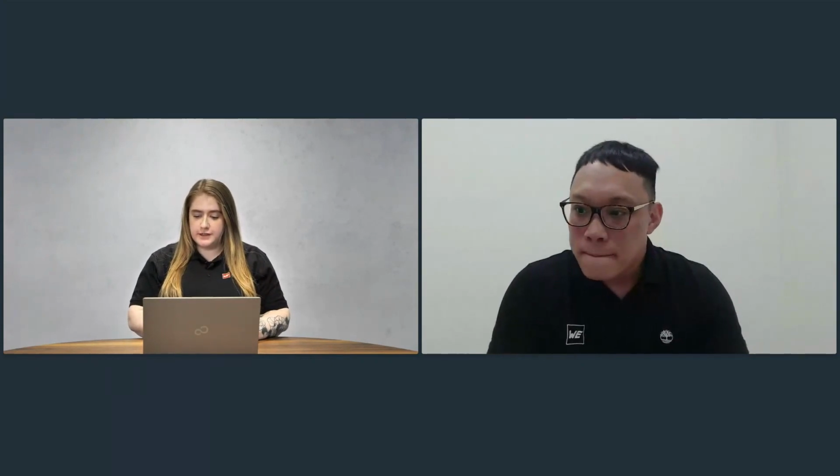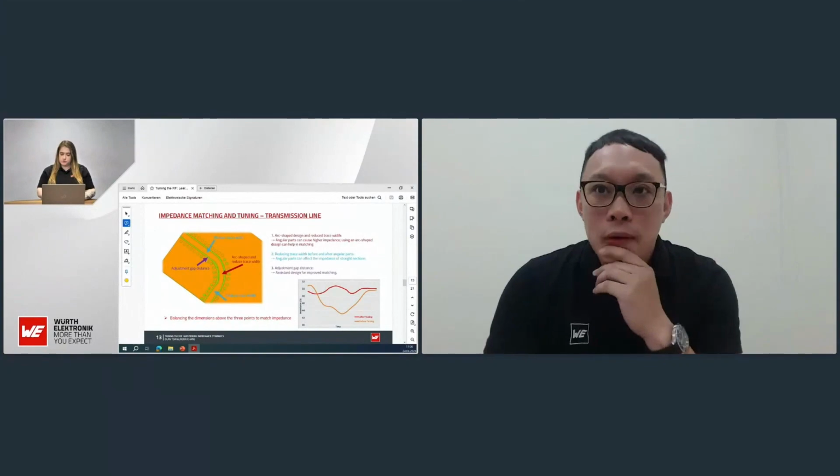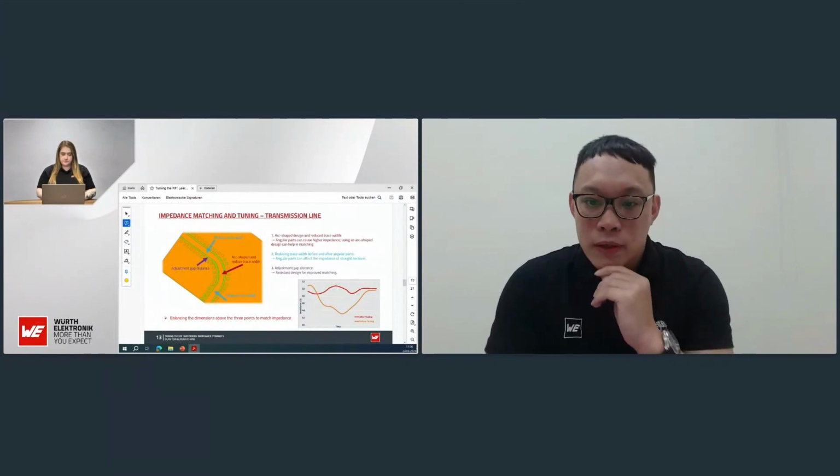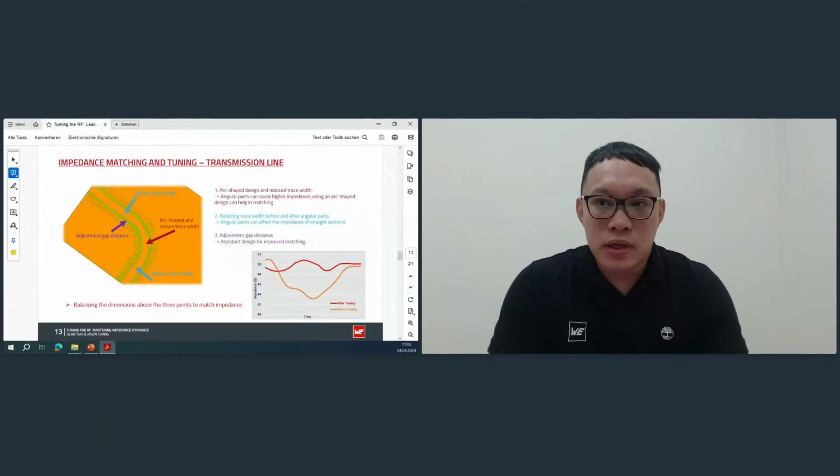The next question is for slide 13. At what data rate frequency does this become critical? What is measured in reality with TDR? If yes, what rise time was used? Okay, the rise time, I remember the setting was 1 nanosecond, and we did not really adjust a lot from the basic setting of the software.